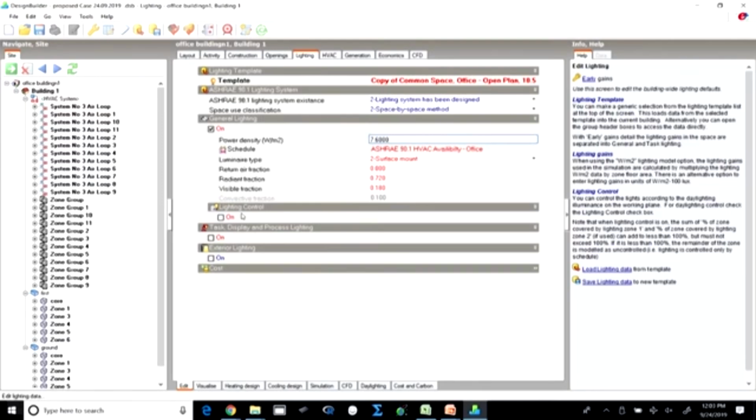It is largely dependent upon the amount of daylight which is available. Sometimes the photosensors will be outside, and the photosensor will sense the amount of light which is available outdoors. In a couple of previous lectures, while we were discussing indoor environment quality, we were talking about the daylight factor DF, and there we were talking about the outdoor illuminance, the amount of light which is available outside.